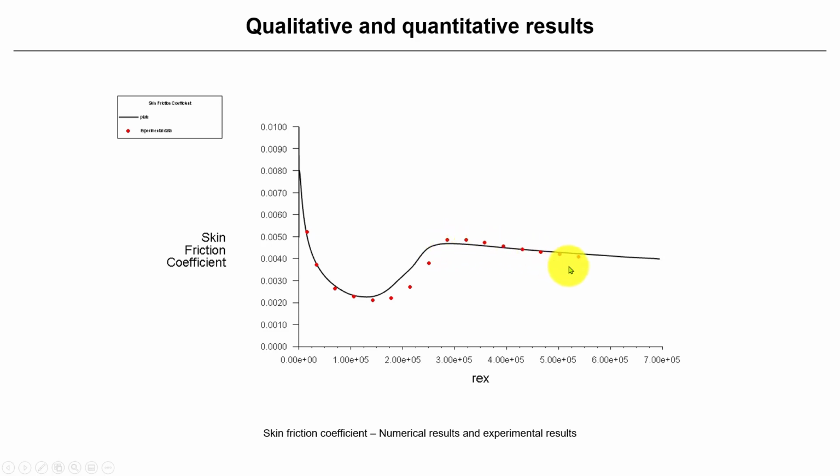What is interesting is that if you run this case using a fully turbulent model, this numerical line will be fully turbulent, and if you use a laminar model, it will just follow the laminar line. So this is the problem with these cases. This is extremely difficult to capture. You need very well calibrated models and very fine meshes, in particular normal to the wall, but also in the streamwise and spanwise dimensions.